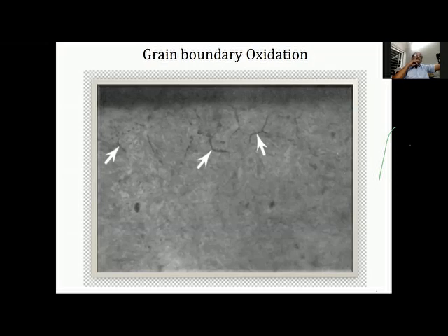Steel making involves, in the final stage, the removal of oxygen by deoxidizing agents. These are typically ferrosilicon and ferromanganese. Those elements have a higher affinity towards oxygen compared to the iron, so they will get preferentially oxidized and form slag and float away from the liquid bath. Now, the steel will be quite okay then, with reduced content of oxygen.